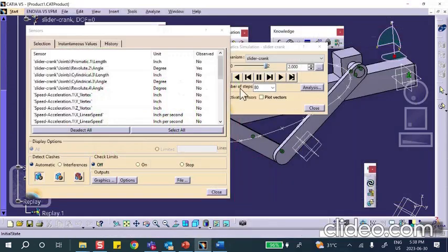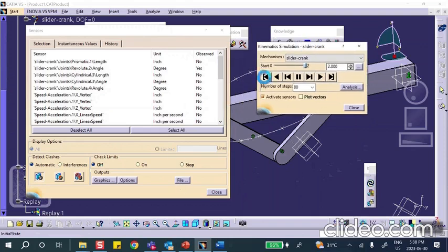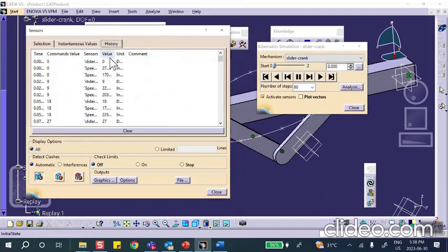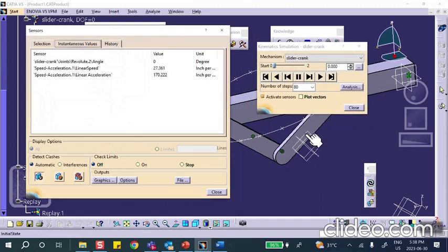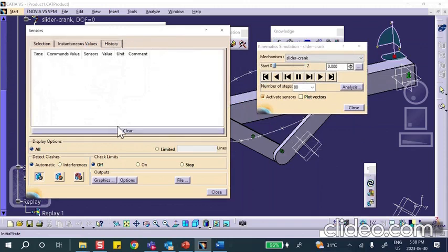Suppose I want to generate the velocity of this point versus the acceleration of that point. So it's not versus time. Those plots that we just stored were versus time. So what you do is, first of all, you rewind. You clear the history. See that? You clear history tab, clear it. Okay, let's go back here. History tab, see history tab, clear it.